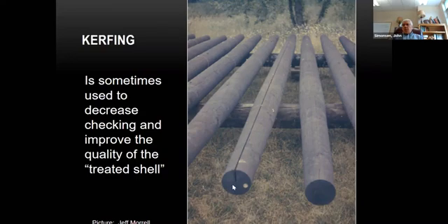Now what happens is when you get conditions that ordinarily would cause checking and cracking, that kerf will just open and close with humidity, right? Because it's the humidity and swelling and shrinking that'll cause the wood to crack and check. So the kerf will just open and close.